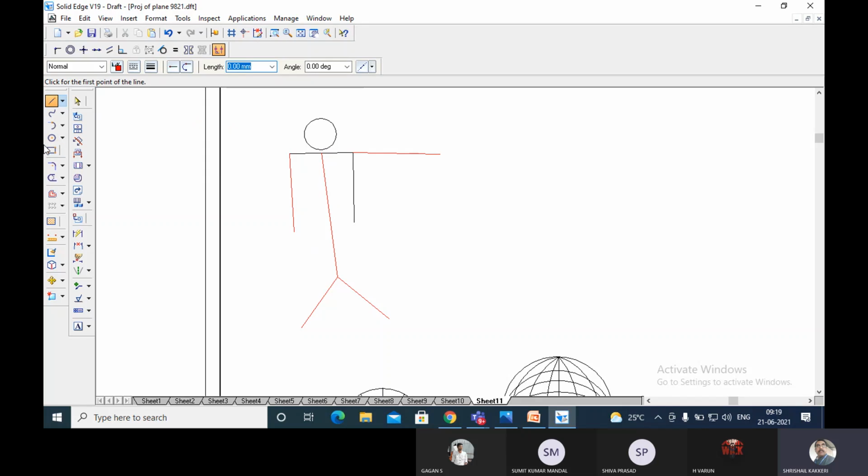And you are able to carry the load, the weight like this, whatever it is, 60 kg or 70 kg. Is it possible to carry the load of 60 kg here by extending your arm horizontally? No, sir. Yeah. And in robotics, it will be considered that when you lift the load by extending the arm like this, the mechanical stability will not be there. The results will be erroneous. The repeatability and accuracy will not be good.